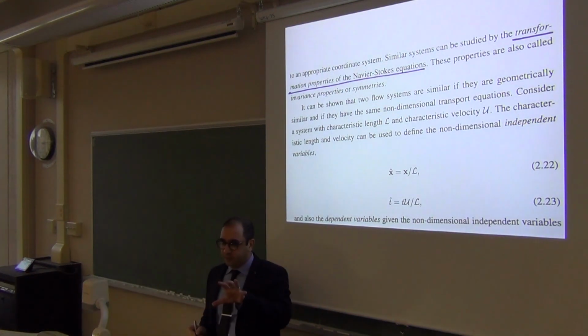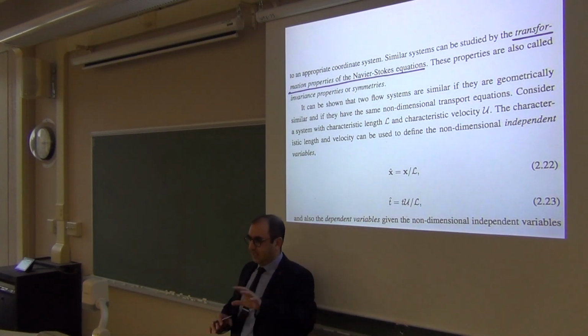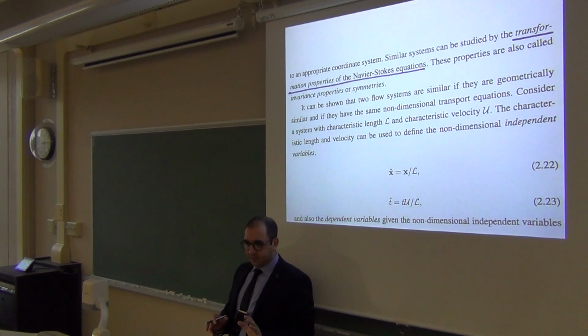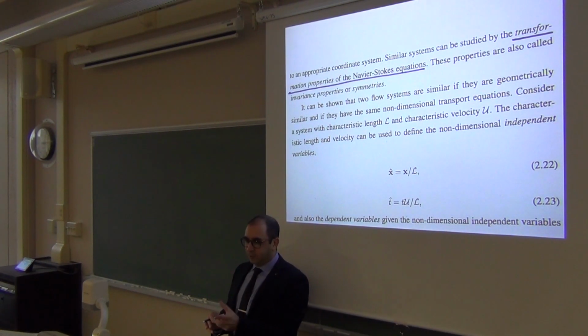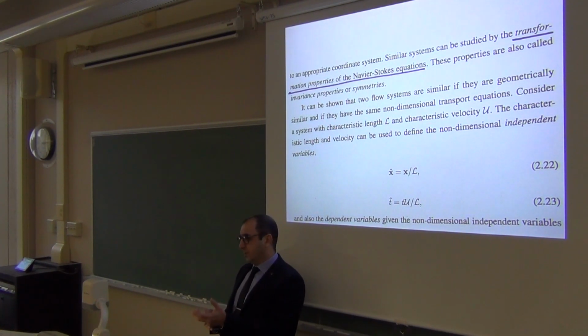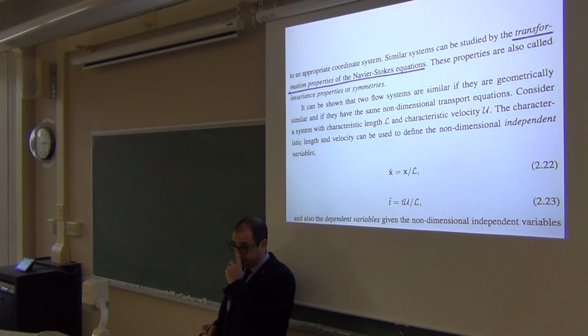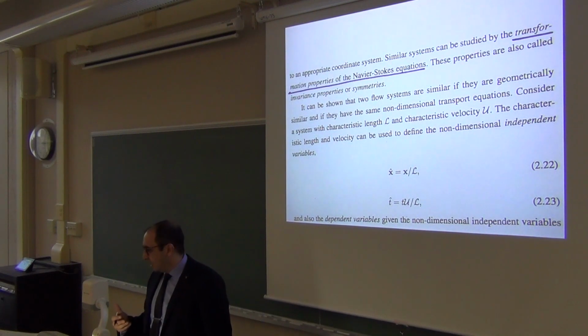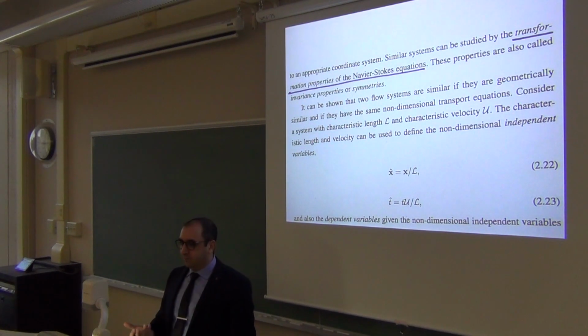That means if you take the equation for the full scale and somehow normalize it, it would look exactly the same as the normalized Navier-Stokes equation for the smaller scale or other scale model. In fact, it's the same equation that gives you the similarity of flow between the two. Right? Otherwise, how could they be similar?